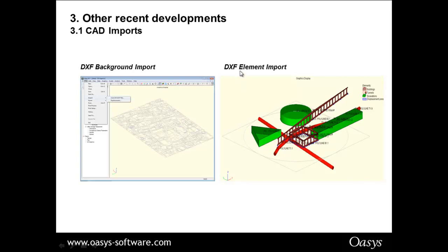So actually you can import everything from DXF. So if, for example, I ascertain a layer to the lines which are associated with buildings, the lines which are associated with tunnels, and the lines which are associated with excavations, and I import that into Xdisp, immediately I would produce an image like this, and then it's up to me to input the tunnel properties and various other things. But at least in terms of the dimensions and all the coordinates, everything's inputted very quickly and easily.